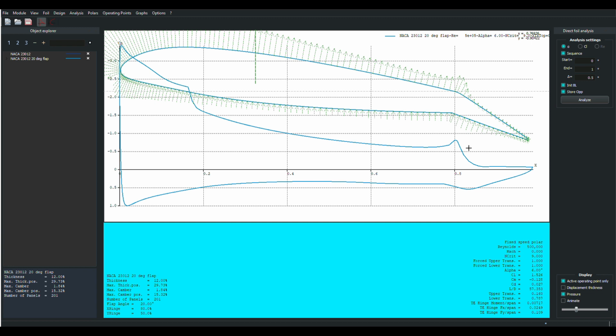So here we are. We have evidence here that this classic setup for hinging control surfaces for low-speed, foot-launchable aircraft is a bad plan, because you create a pressure environment that the flow has a hard time getting through, and you get separated flow, premature stall, laminar separation bubbles, all kinds of problems. And now we're about to understand why the flat plate flap back here instead of this thick thing actually works, even though it's less effective.